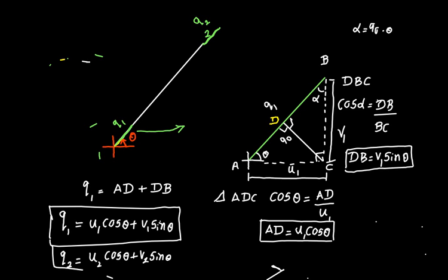Having derived the expressions for displacements, now I can define the strain energy for a single truss element, which is actually a bar element. So in the next page, the expression for strain energy. Now we know what is the expression for strain energy, which we have already derived. It is going to be 1/2 into U transpose, that is the displacement matrix transpose, followed by the stiffness matrix, followed by the displacement matrix. Now, how do I write this expression?